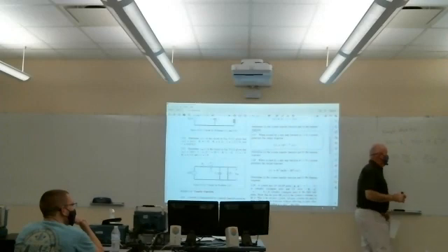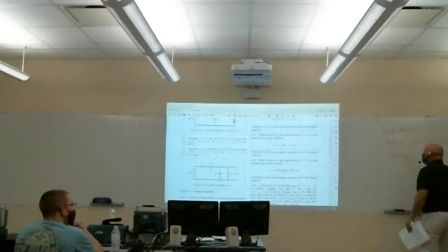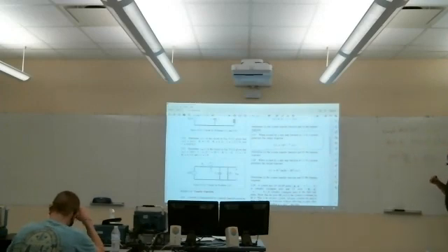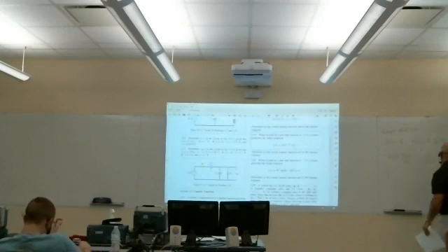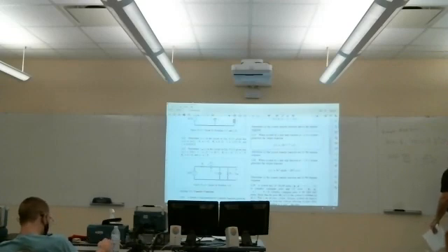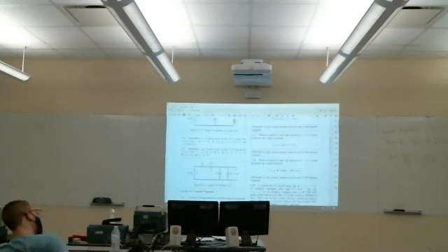Now, this is part A, find the system transfer function. That was easy. To find the impulse response, we're going to have to do a partial fraction expansion on this, their Fourier transform pair. This is kind of a nastier one because it's a repeated root. So it would be A1 over s plus 3 cubed plus A2 over s plus 3 squared plus A3 over s plus 3 in general.